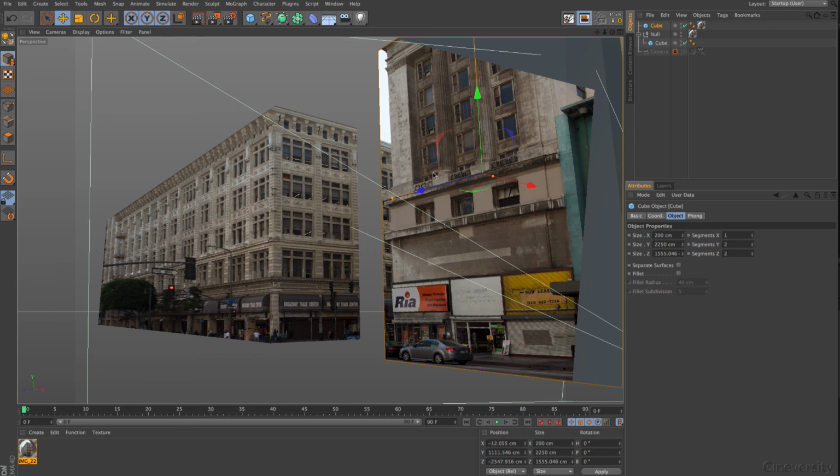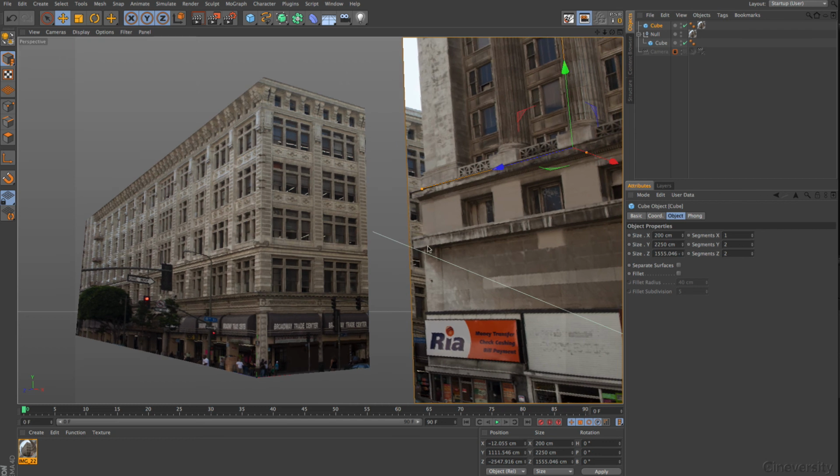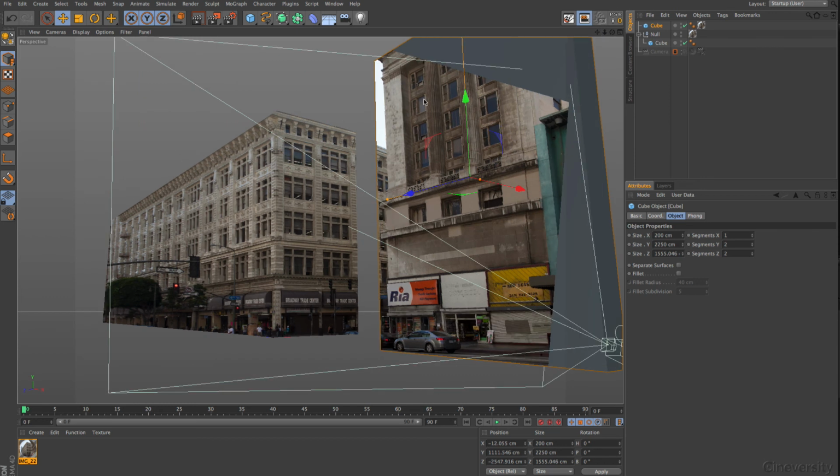So now comes, of course, the $1 million question. Should I go with this area here and create tiny little geometry? Is the camera move really unveiling that I have maybe just a fake here? And should I go just with an alpha channel and cut this out so I get a nice object border? This is up to you. I have shown you how that works. Just go with the projection camera, copy that, render it, paint this on it. You can do this even in the original picture and set the alpha channel into it.